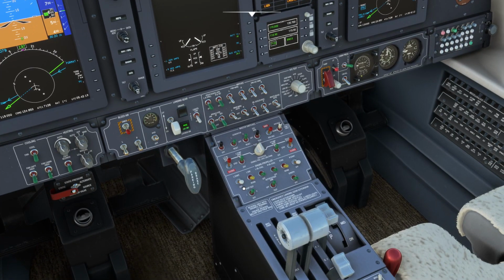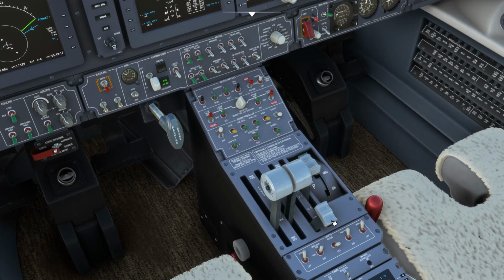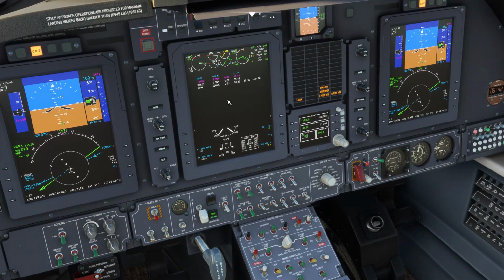Right, start. NG at least 13, which is now. Move it up. And the engine is kicking in. Our ITT, we remember, is supposed to be below 1000. Our oil pressure is supposed to be getting up.